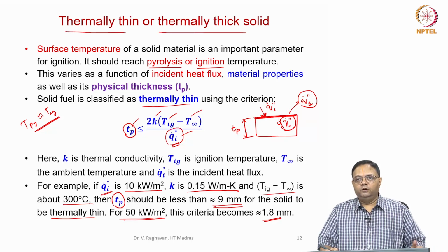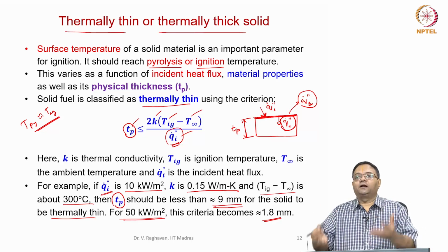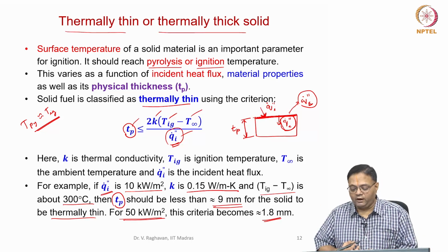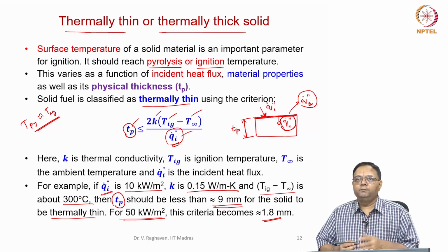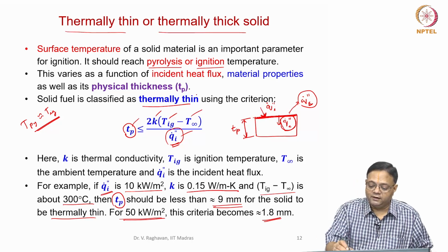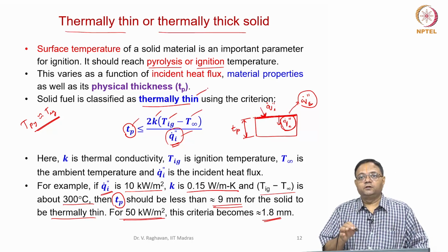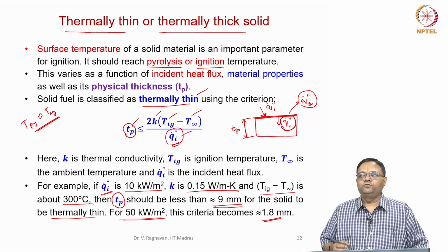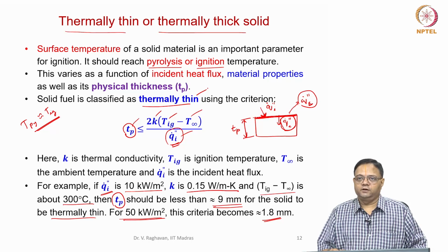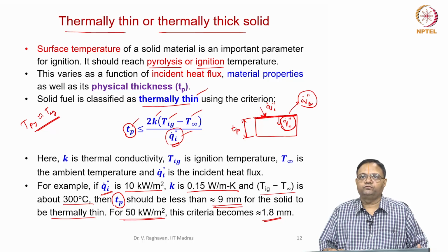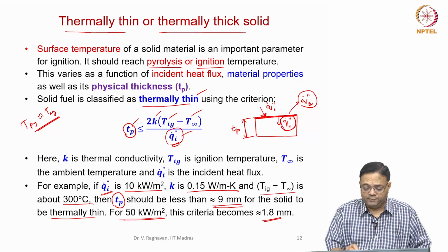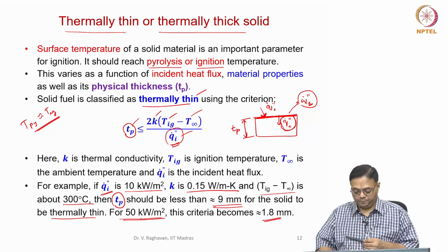Then, to avoid the conduction analysis inside the solid, I need a thinner and thinner material. So, thermally thin is different from the thickness. I cannot say always that if you have a 2 mm sheet, it is thermally thin, because it depends upon what the heat flux is.